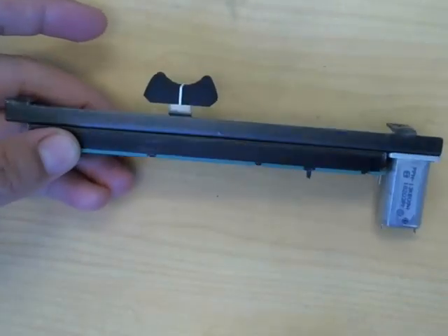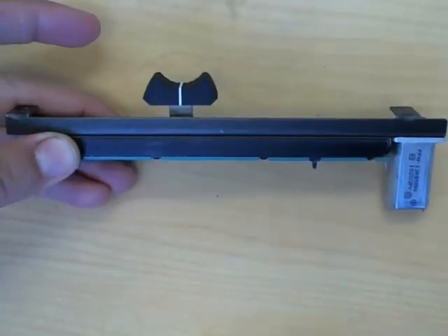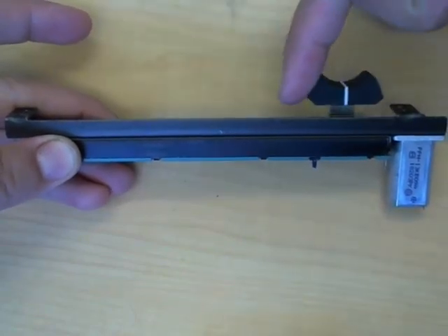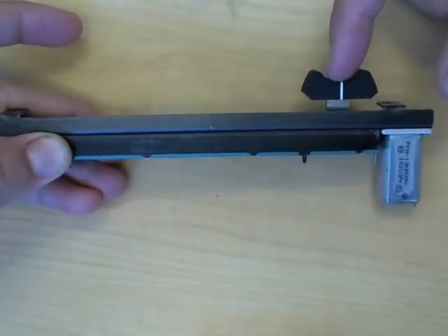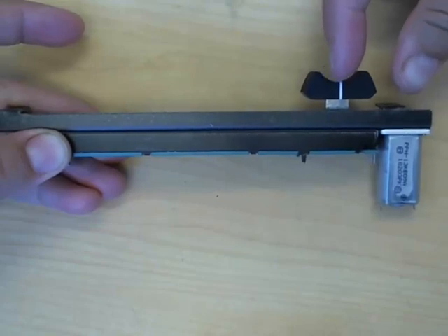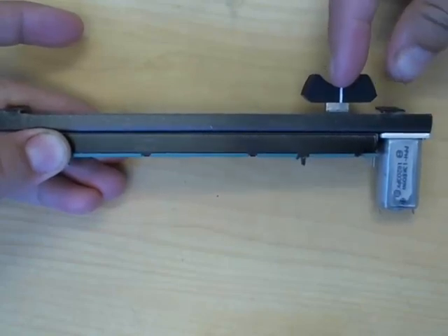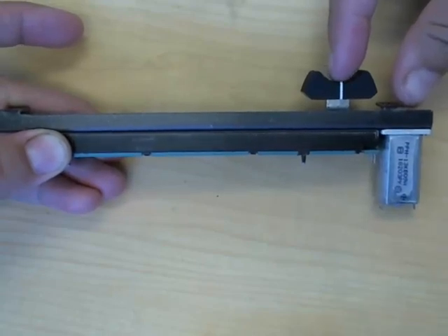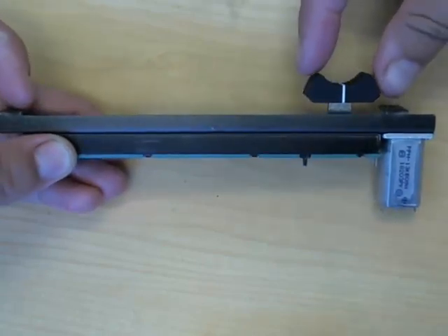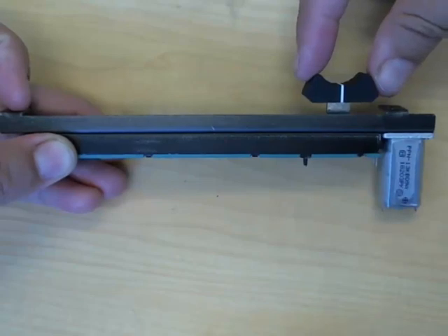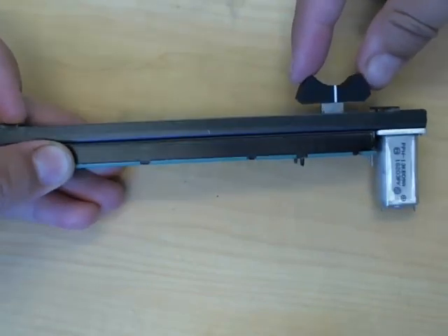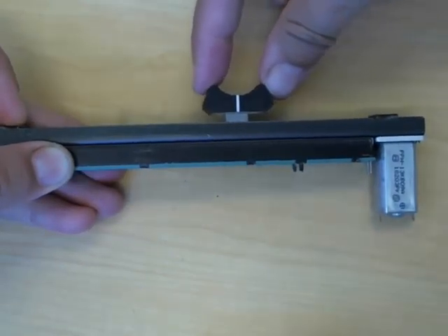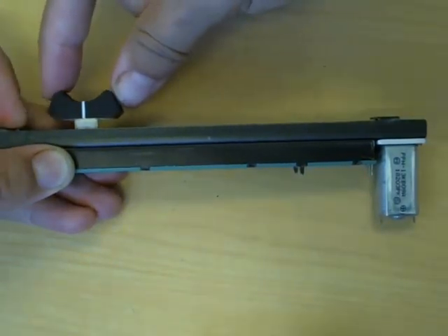This device is a kind of prismatic joint. If I slid the slider all the way to the end, this distance here between the slider and the center of the motor where we would draw our joint, that would be A, the link length. And D, the joint variable here, is the distance that this slider has slid along its track.